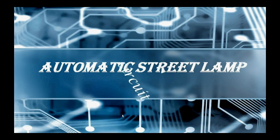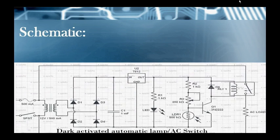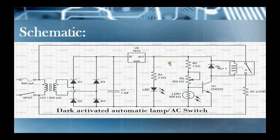Let me show and explain the schematic circuit diagram now. The circuit needs a DC excitation of 12 volts. So I powered the circuit with a 12 volt 500 milliamp transformer and a bridge rectifier, and I used a 1000 microfarad capacitor and a 7812 IC for better DC output. I connected the LED with a series resistor across the two output terminals as the indicator of the power supply.